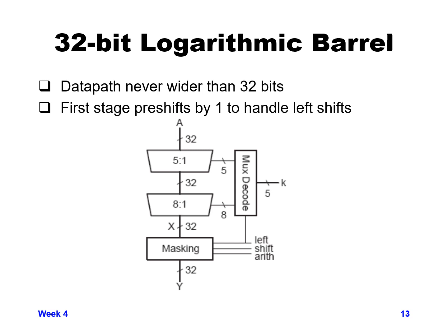So we could either do a rotate of 0 or 1, depending on if we're doing the pre-rotate, and then we can rotate by an additional 0, 1, 2, or 3 bits by doing that 5-to-1 mux at the beginning. And then when we're doing our 8-to-1 multiplexer, that's going to do rotating by multiples of 4 bits.